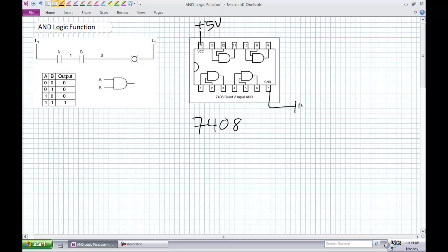One thing I failed to mention in our timing diagram discussions is you may have an input A, a digital data stream on input A. What if you have nothing on input B? We talked about a constant high or a constant low. What is an open being read as for a TTL circuit? Is it being read as a 0 or as a 1? Your output conditions will change based upon how it's reading an open. It's critical to your understanding: you can't just leave these things dangling and expect the functionality to stay the same. You'll be doing that in lab.